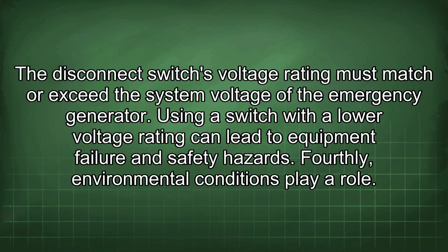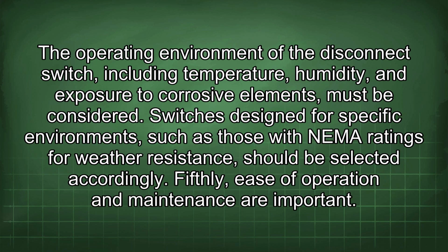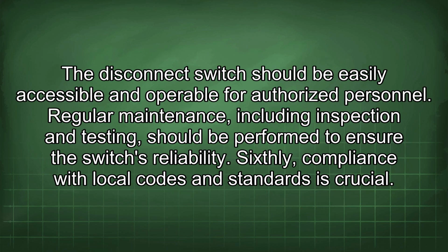Fourthly, environmental conditions play a role. The operating environment of the disconnect switch, including temperature, humidity, and exposure to corrosive elements, must be considered. Switches designed for specific environments, such as those with NEMA ratings for weather resistance, should be selected accordingly. Fifthly, ease of operation and maintenance are important. The disconnect switch should be easily accessible and operable for authorized personnel.